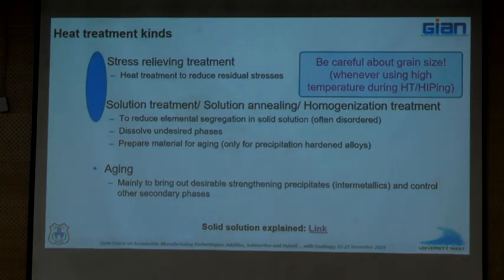If you are looking at wrought or cast Inconel 718, it calls for a solution treatment which is, I think, 1 hour and 15 minutes long. And then it has a 2-step aging, which is 8 hours plus 8 hours. So, can you imagine, you are doing almost 20 hours of heat treatment, including heating and cooling, to eventually get what you have built in a form that is usable. 20 hours, right?